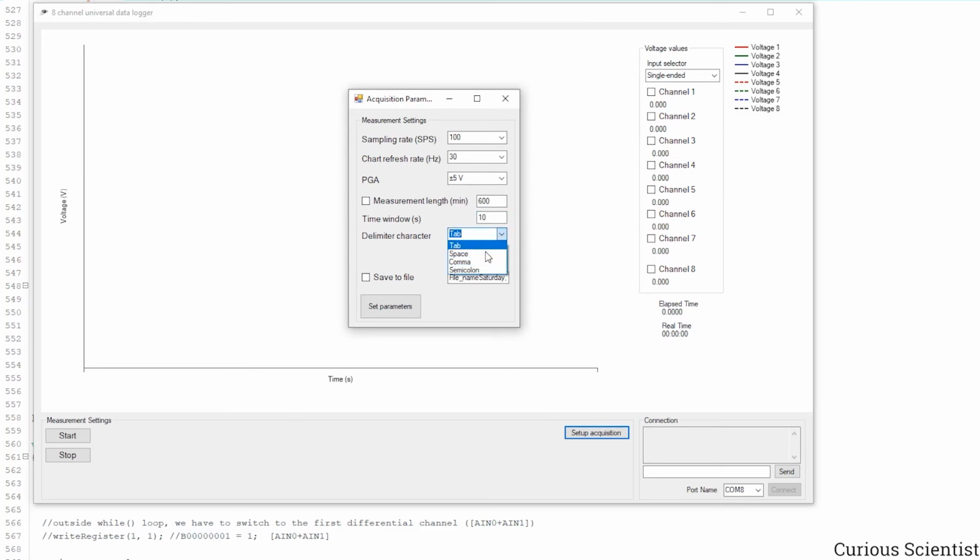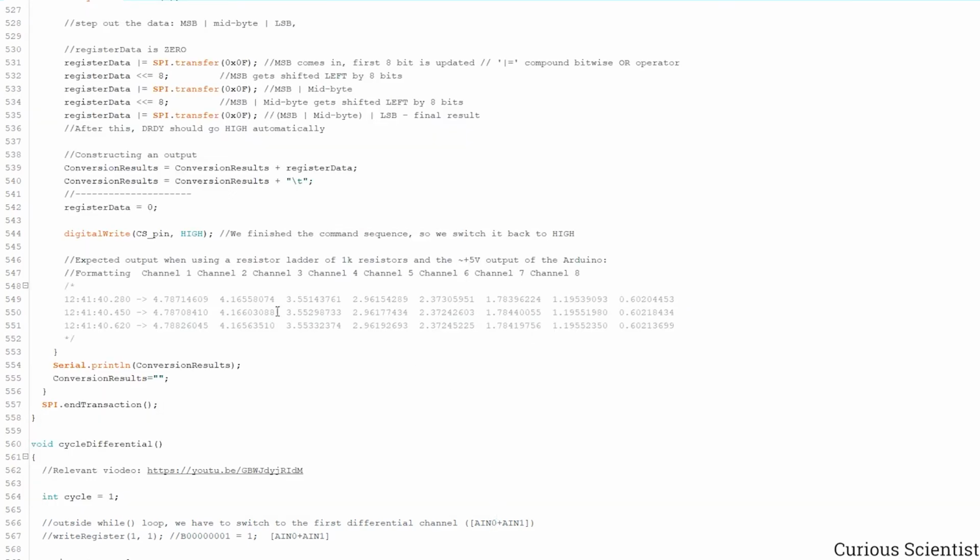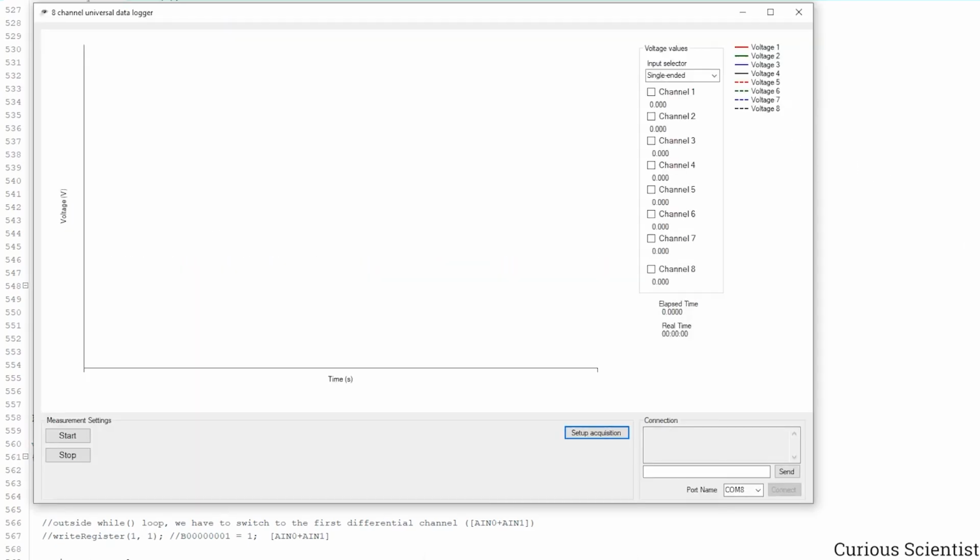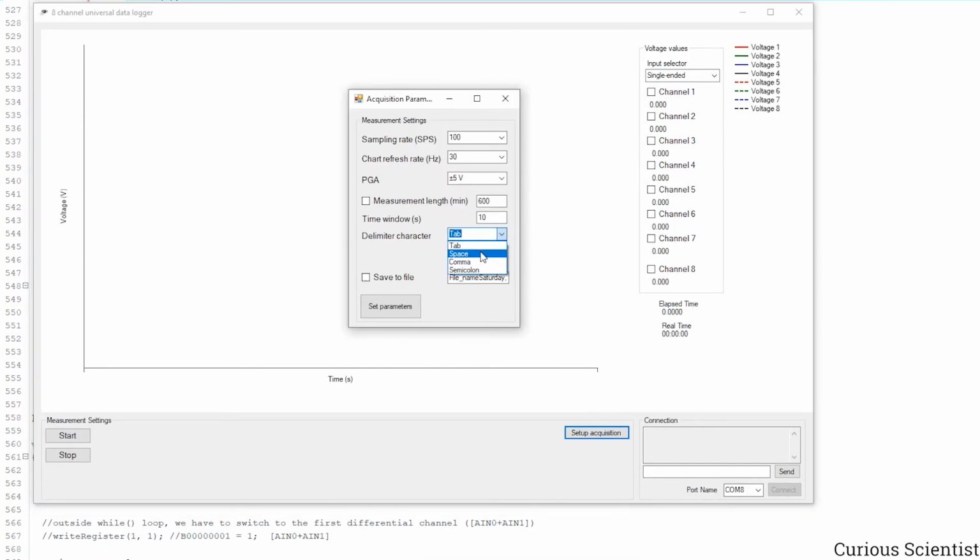And then this is for, basically, for other commands, that if you write another software or you control another AD converter, you can still have the data formatted in this way, or for example, you can separate everything with a comma and so on, and you can tell it to the software. And so here I just use the most popular separating or delimiter characters, and I will use the tab, and here we just have some predefined file name. You can save all the data in a file.